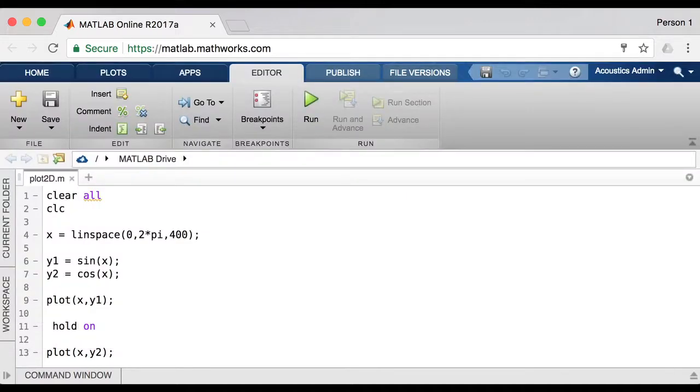Every time we run a MATLAB script using plot, MATLAB will give us a plain figure and we will have to go through the entire process each and every time. So there's a way by which we can edit the plot directly from the script. We can do that using handles. When we want to edit a particular line in a figure, we should be able to tell MATLAB to edit that particular line and not any other.